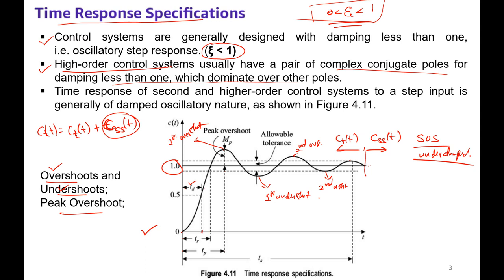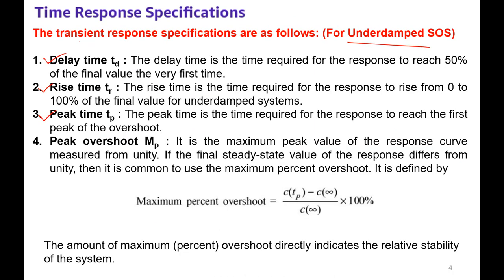This is the maximum value. If you compare with any other values in the amplitude of the variations of the sinusoidal wave, you can observe here, this is the maximum value. The time taken by the response to achieve this, we also call the first overshoot. Time taken by the response to achieve the first overshoot or maximum peak value, we call it TP, peak time. So how we will define it, we'll see.